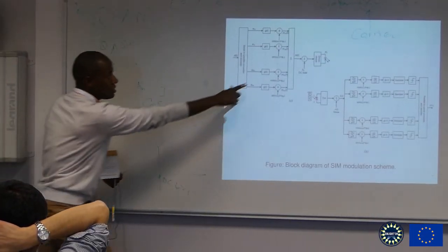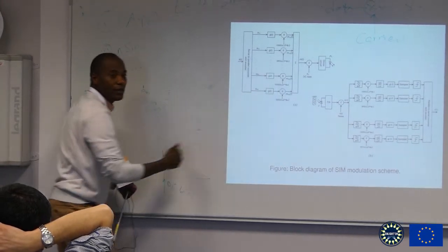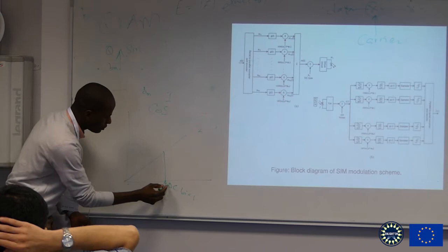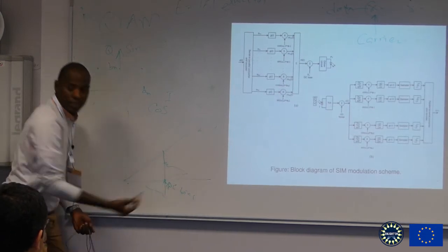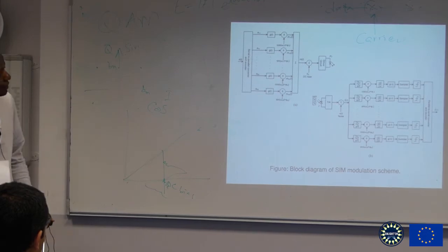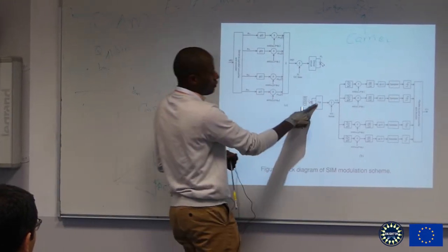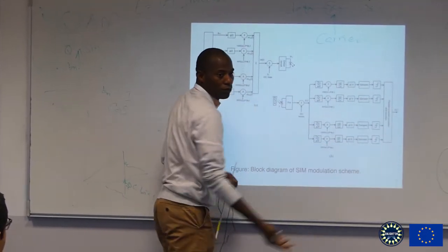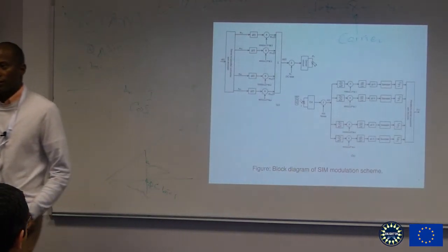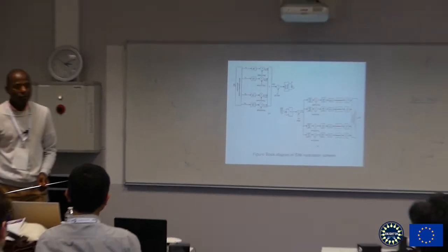That's DC, because the signal we are getting by the time you add all of this together is unipolar, but real. And then it becomes something like this. And that's what we get. And that's subcarrier modulation. You get to the receiver side, you do exactly the opposite. Photodiode, you do the opposite and you get your information out. It's as simple as that. Any questions? Have I lost anyone? Good.